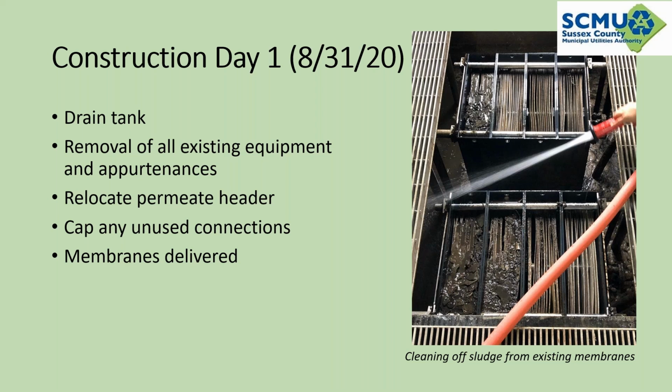You're probably not getting great treatment, or as much flow as you'd like through these because they're totally caked up. As part of the process, we wanted to make sure everything was as clean as possible before we removed the membranes from the facility. We wanted to keep everything within the train such that we could haul that to one of our other facilities.